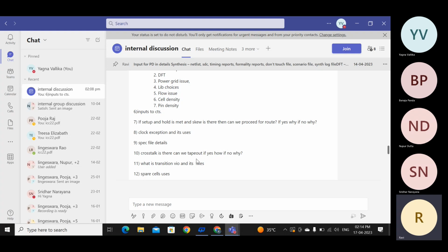So look at all these inputs, your CTS exception file, your clock spec file, which trees you need to construct, and also your clock balance points. All these you have to check properly, which metal layers, etc., and ensure that they are all done properly. Okay, and construct the clock tree for the fastest frequency.